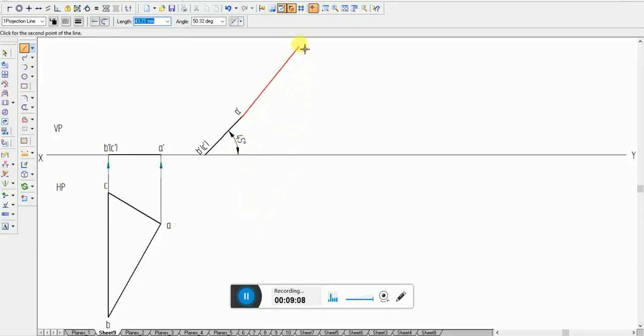One thing you can see is here there is an icon called alignment indicator. In case this alignment indicator is off, then you cannot see that dotted line which comes. I'll show you. See here, the dotted line is not there. The reason is that this particular indicator is off. So now I'll turn on the indicator, and now see, the dotted line is back. That is, it is indicating that it is properly aligned. So I'll just click here, join this back to here.